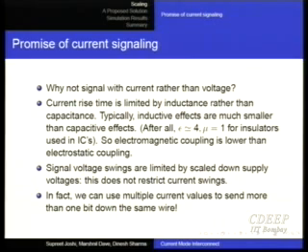So then what is it? We are now sitting here and dreaming about it and drooling, saying current mode has all these nice things. First, I am not charging up and down the line, which was unnecessary overload on me, therefore I am not spending so much power. The second thing is that when I inject current at one end, because the voltage is not changing, no current goes to charge parasitic capacitance. So as soon as I inject current at one end, there is very little delay for seeing this current come out at the other end.